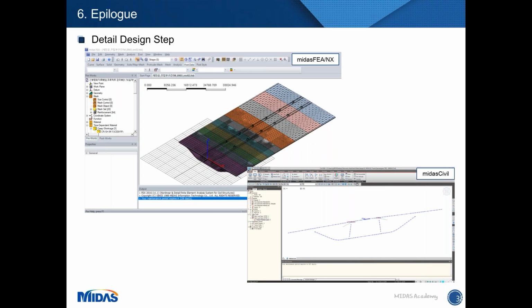They could be punching shear of the slab, shear resistance between the flange and web, checking displacement of the cantilever zone for serviceability, and so on. These were considered in the detailed design step. In that case, our design team did additional design work to get more precise analysis results. They used another software called MIDAS FEA NX as well. This software supports various options for the detailed analysis.